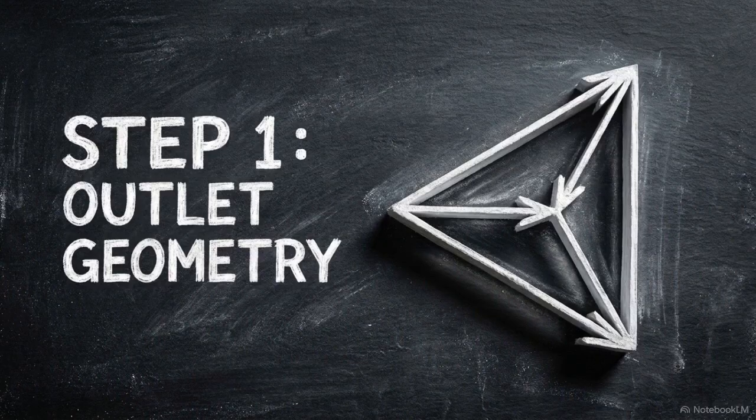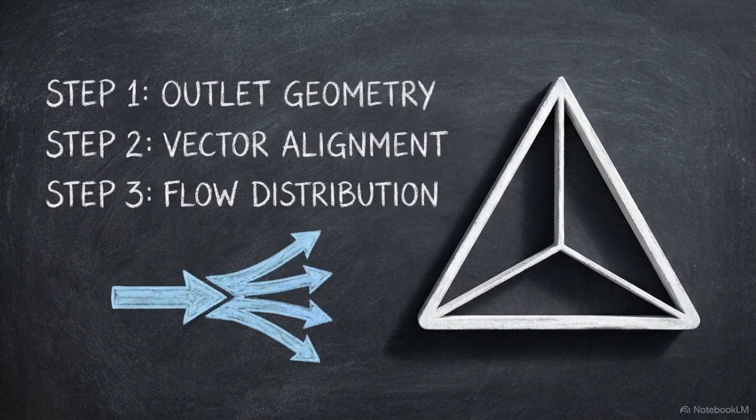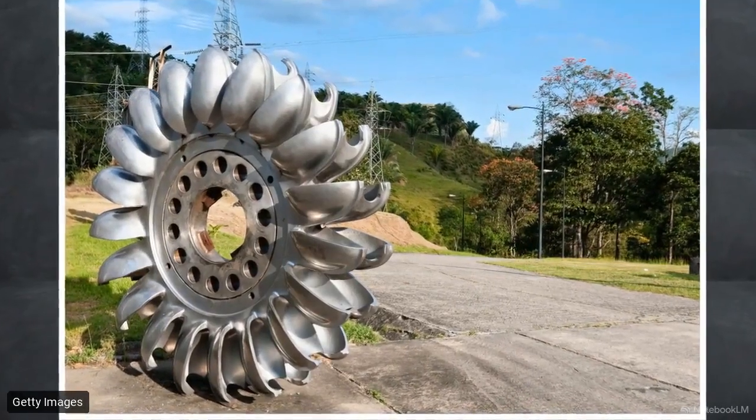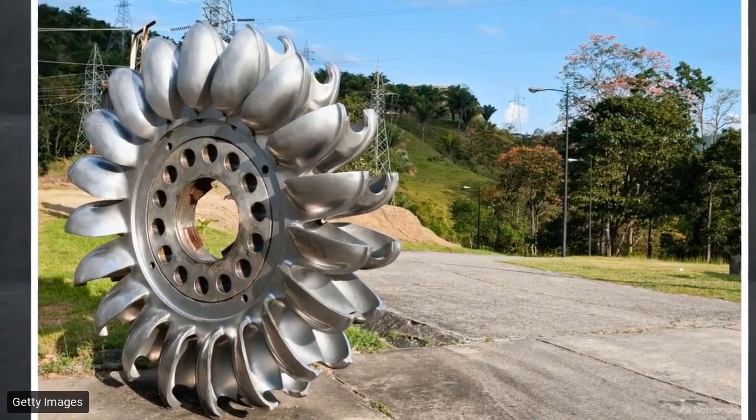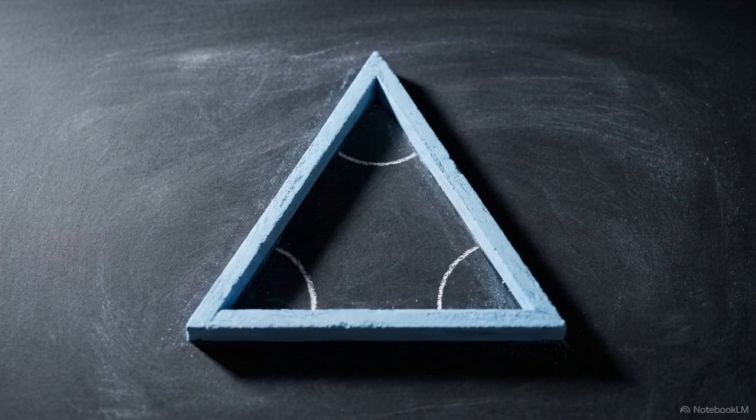Before you finish, review these 3 technical requirements for Pelton Numericals. First, always convert the jet deflection angle into the bucket outlet angle, phi. Second, verify the sign of vw2 by drawing the velocity triangle. And third, for multi-jet geometries, always divide the total discharge by the number of jets before calculating the jet area. Mastery in fluid mechanics relies on successfully translating physical machinery into an accurate mathematical model. Keep drawing those triangles, and I'll see you in the next session.